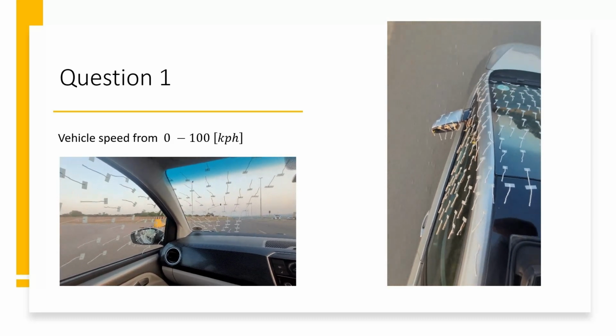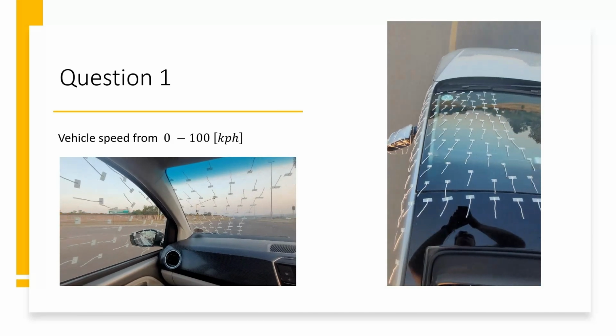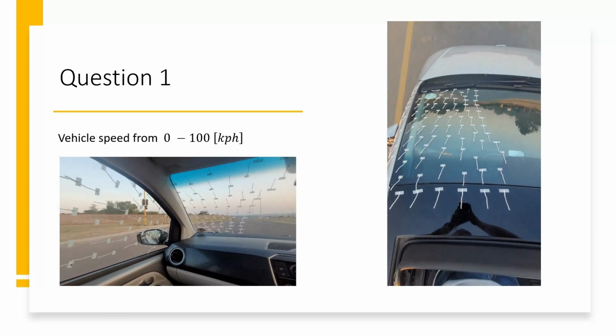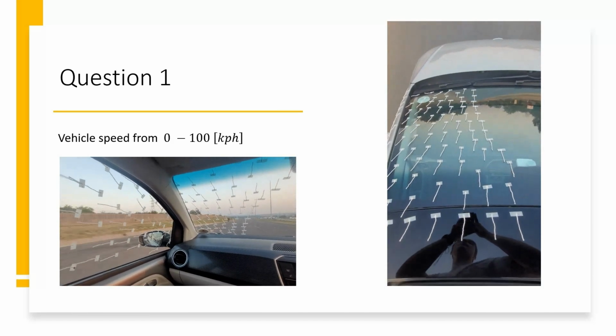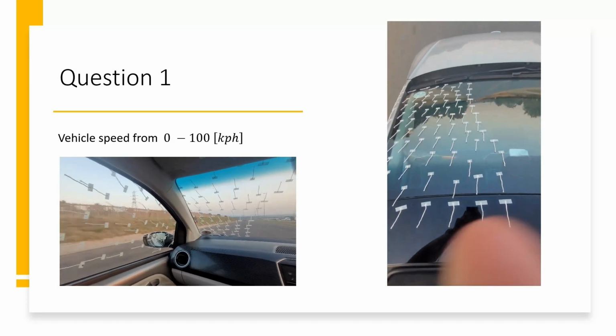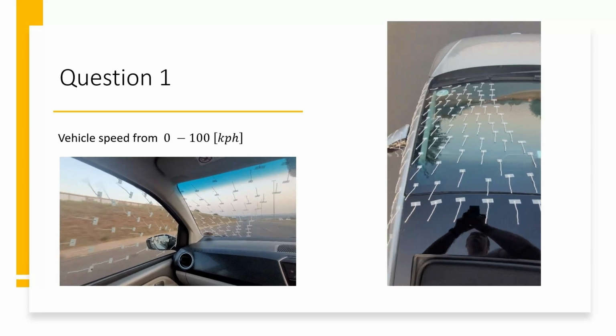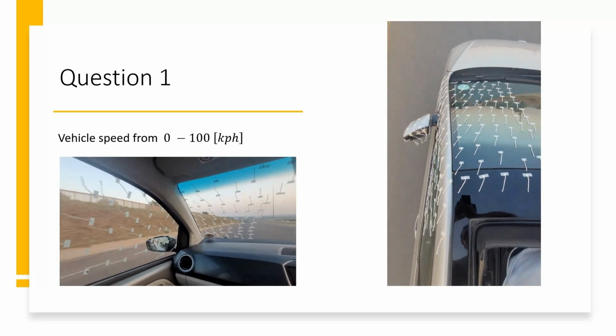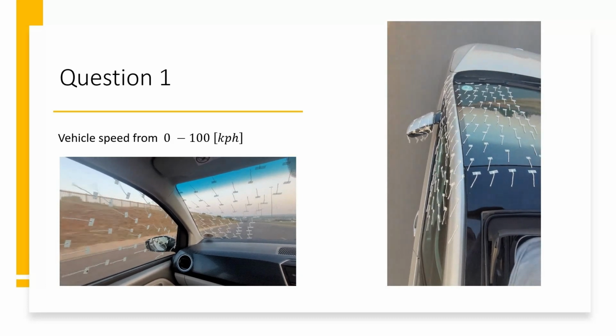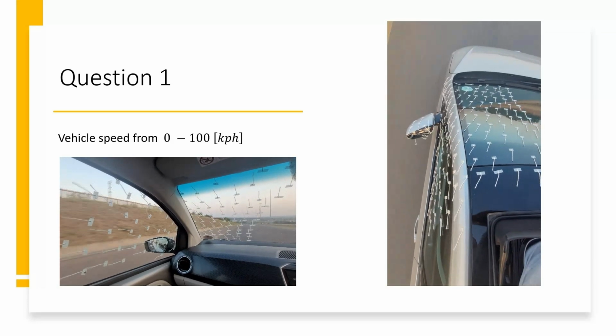Observing the flow nearer to the top of the window as it gets closer to the A-pillar and the roofline, where there is some flow separation happening, the tufts start to move around and change direction more rapidly, while having a general upward trend towards the roofline and A-pillar. This indicates more turbulent flow and that the flow is moving down the side of the vehicle as well as up and over the roofline of the vehicle.